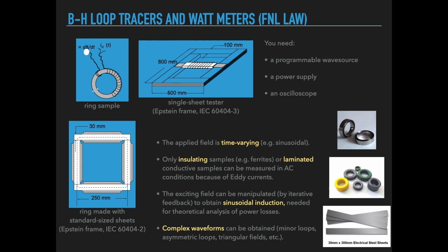As long as the applied magnetic field is time-varying, it is not necessary that it is sinusoidal. For example, when magnetic losses must be measured in these materials, it is important that the induction of the material, so its magnetization, is sinusoidally varying with time. But since the relationship between the magnetic field applied and the magnetization of the sample is nonlinear, having a sinusoidal induction requires a magnetic field, an applied magnetic field, that is not sinusoidal in time.